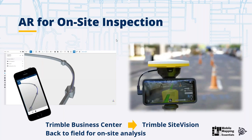Okay, so the Trimble MX7 is a mobile mapping technology, which in general we present as mapping grade accuracy. What does it mean? Well, the performance of these absolute accuracies is mainly the consequence of the kind of IMU, or inertial platform, if you like, we have in the system, and the GNSS conditions which the specific MX7 is having at that moment during the mission.